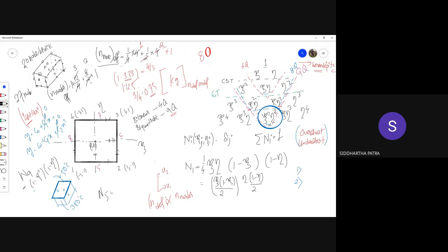But with the serendipity element, you have 4 nodes per element. So that 33% saving that we are talking about has now become 100% saving, or the 25% saving has become 50% saving, which is quite a lot of saving in computational time.